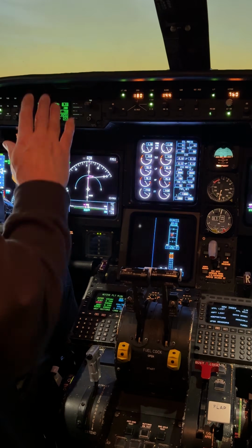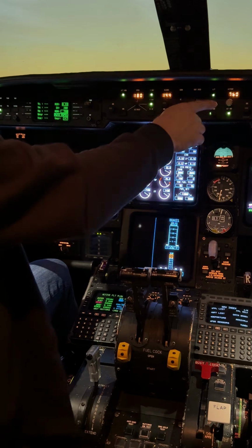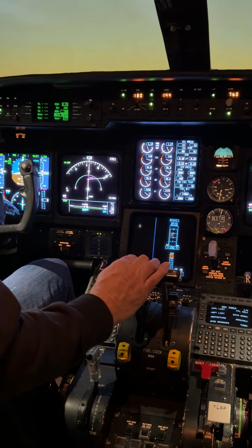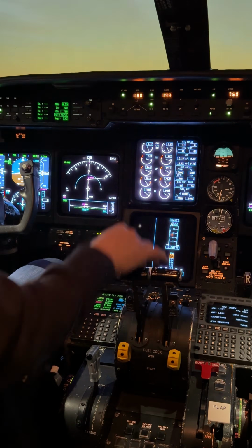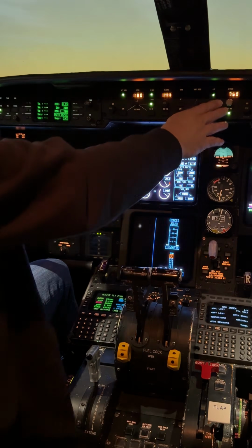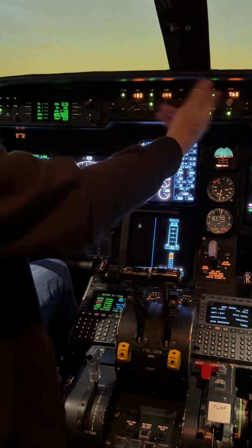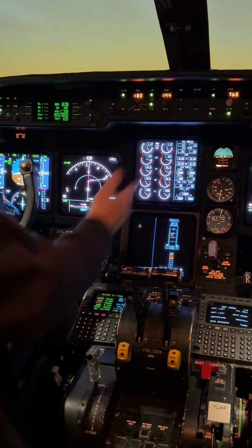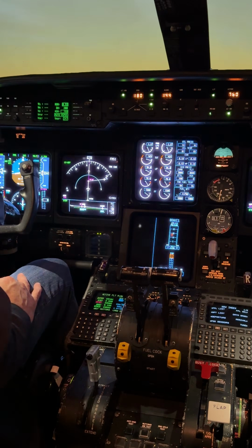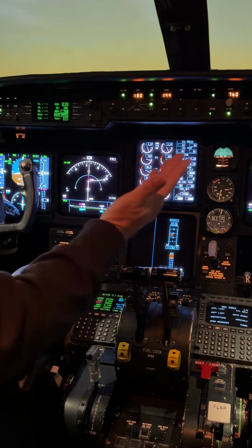When you're doing an RNAV GPS approach, you have to set the minimum first, then press VNAV. Like I said, I've seen people press VNAV and stay at 3,000 feet all the way to the runway. You don't put an altitude in there, it's got nowhere to go. This is your wish list, that's your reality. I'm wishing for 760. I have VNAV and it's going to do what I want it to do. If I had 3,000 set in there, it's not going to go anywhere.